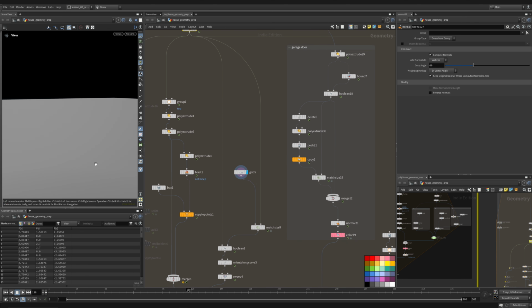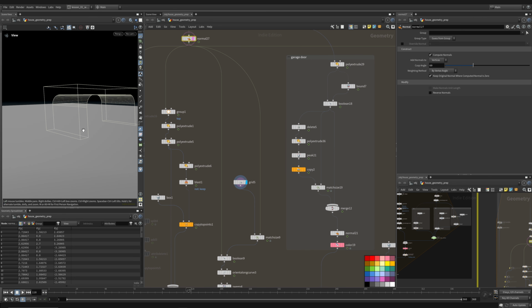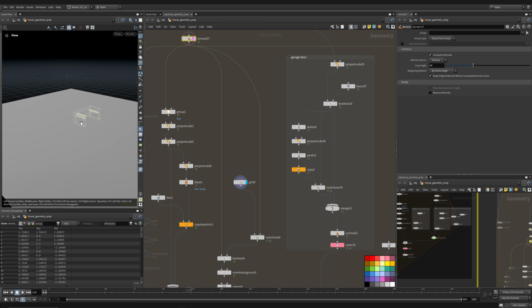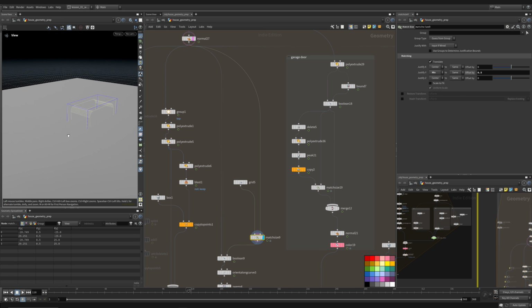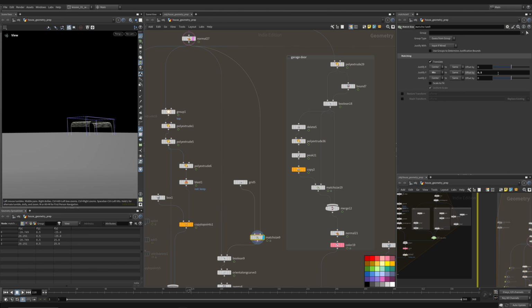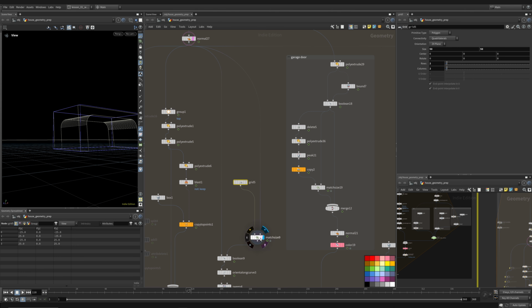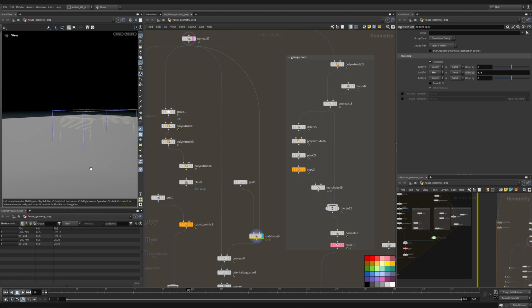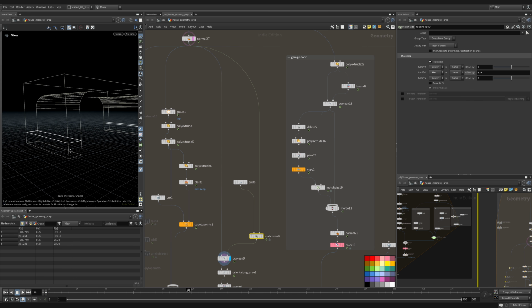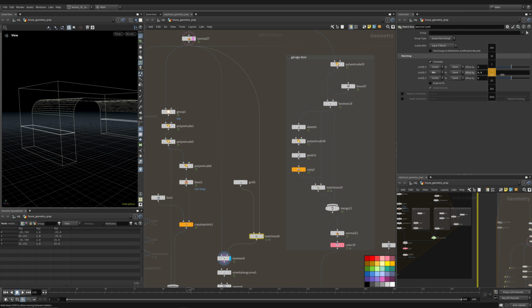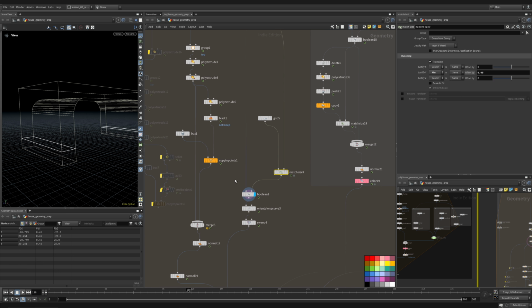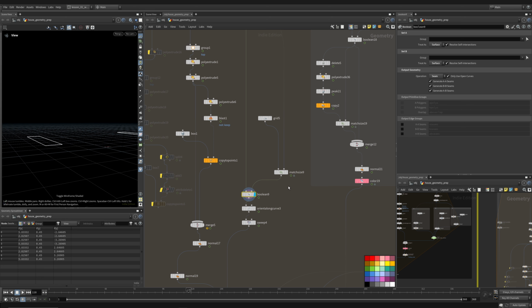So we'll create a grid, which will be our big cutting surface, which we definitely know is bigger than this object. So we do a match size to place it in the middle, which we did a little bit of an offset, actually not the middle. We took the grid, match sized it to the minimum, so we placed it to the bottom, and then we offset it by 0.5. So it will be 0.5 meters, this seam above the floor. We could change that here by middle mouse clicking and dragging. We'll leave 0.45 maybe.